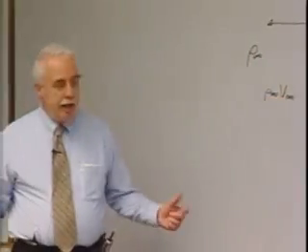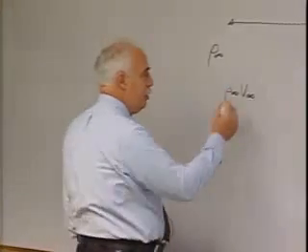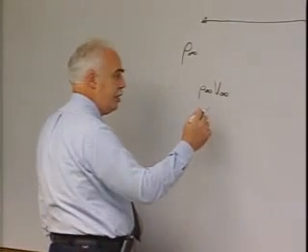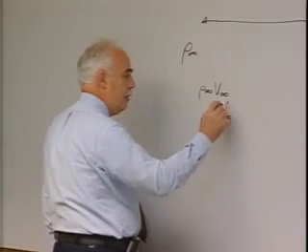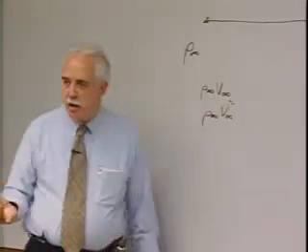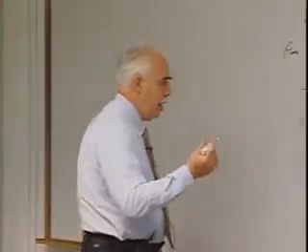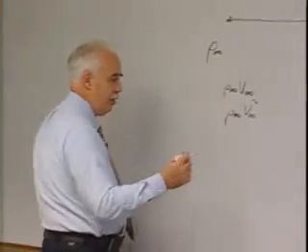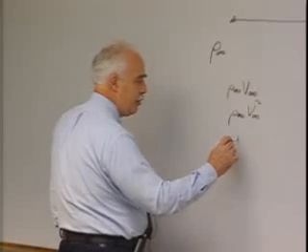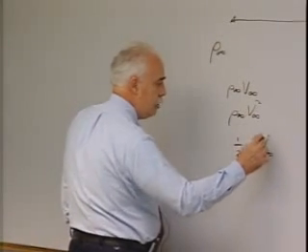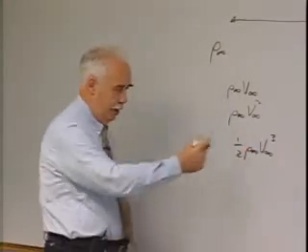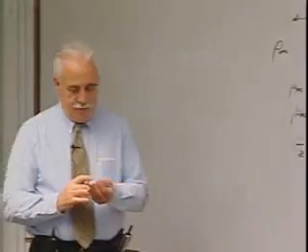The momentum that air has relative to you per unit mass is the velocity. So this is the momentum flux, which basically is the pressure to a very high accuracy. The energy that the gas has relative to you is 1/2 v squared, and so we're looking at an energy flux on the order coming to the vehicle of 1/2 rho v cubed.